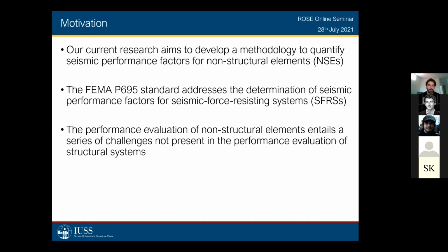elements. So currently, the FEMA P695 standard in the United States addresses the determination of seismic performance factors, but for seismic force resisting systems. So in other words, for structures. It is not for non-structural elements or secondary systems, as they're called in different parts. As many of you can imagine, the performance evaluation of non-structural elements entails a series of challenges that are not present in the performance of traditional structures.